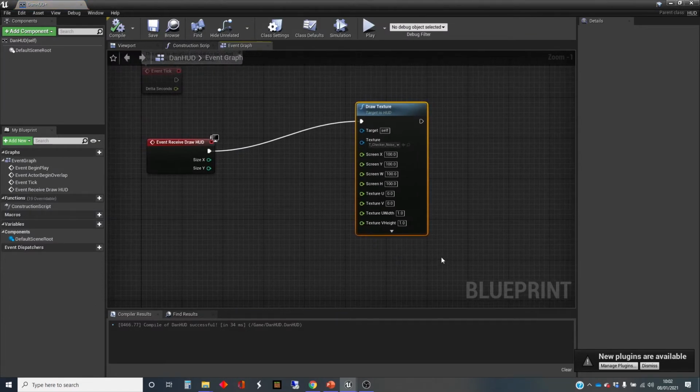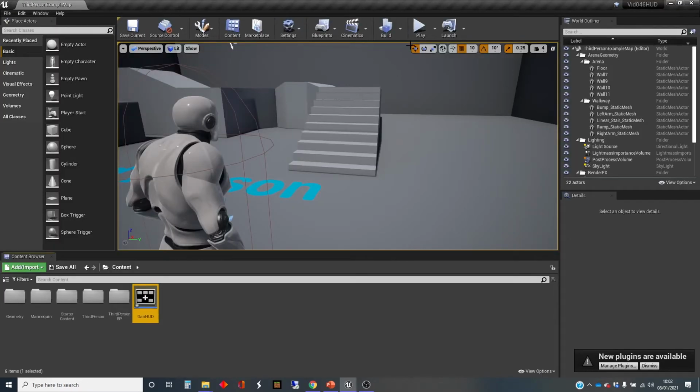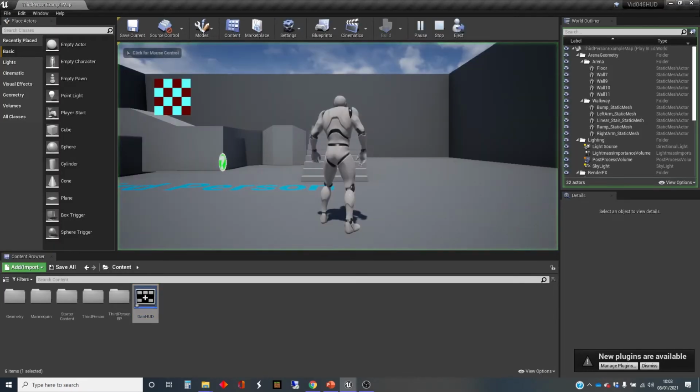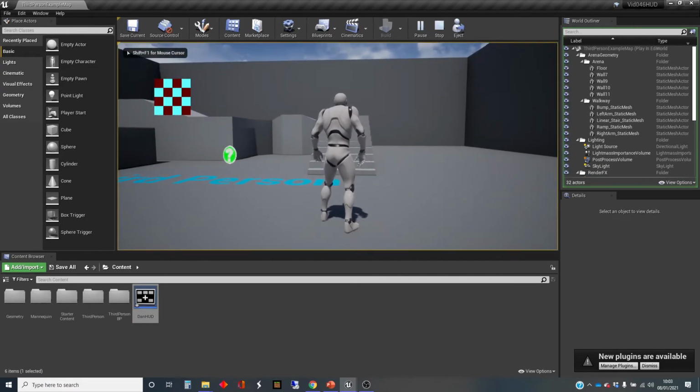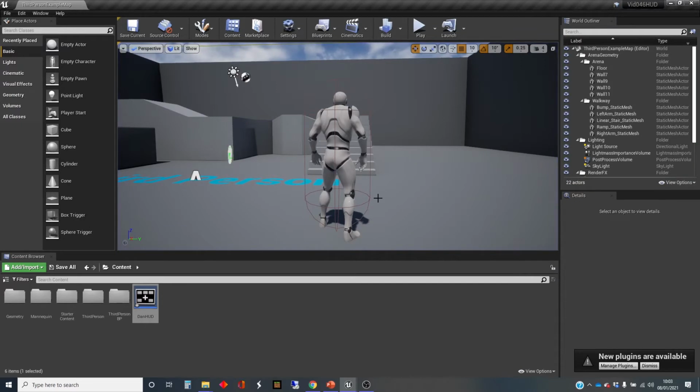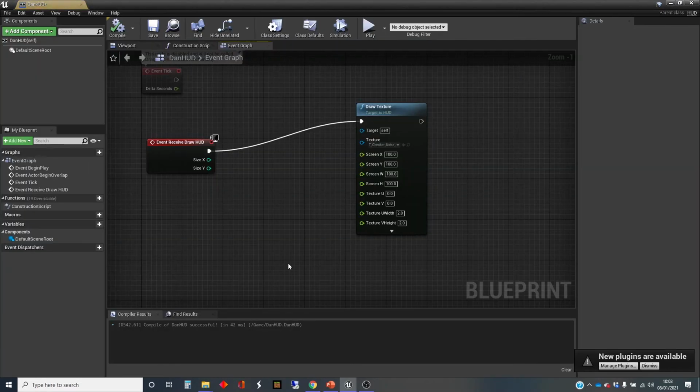So the first thing I'm going to show you is I talked about this texture mapping, and just to prove what's going on there, I'm going to put 2 and 2 in there, and that should be giving us that texture at half size and then double across. There we go, more of a checkerboard. But that's not what we wanted it to look like. Actually, we want it to be a narrower bar, so its height is less, but it stretches further across.